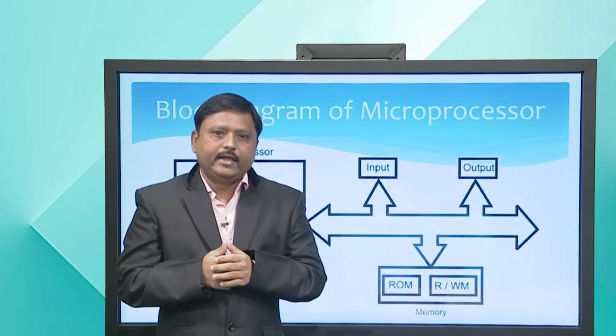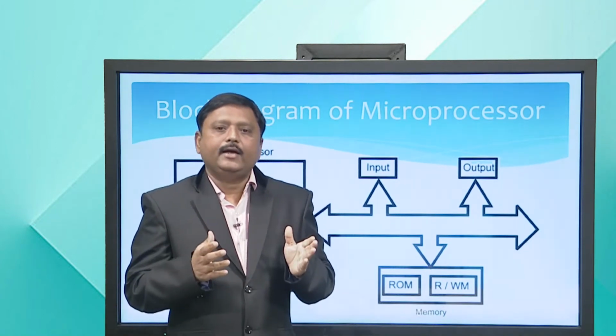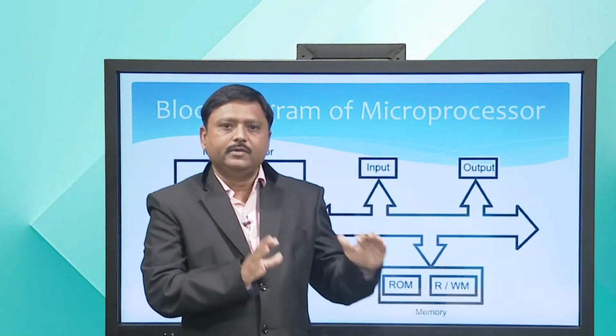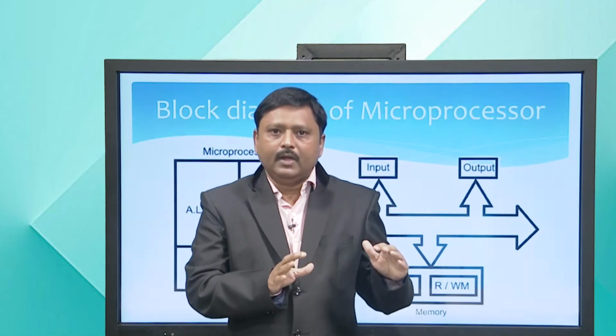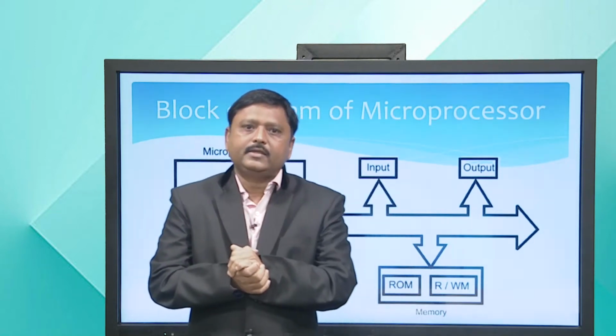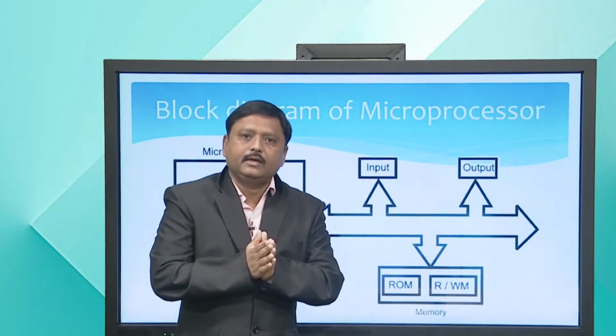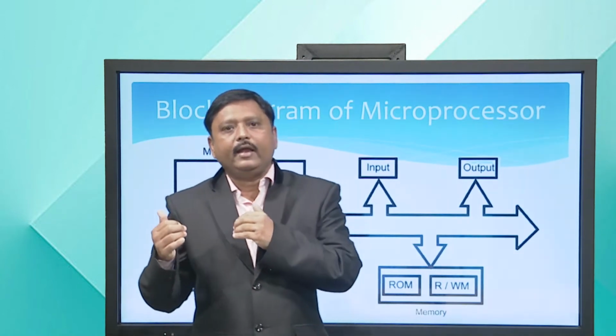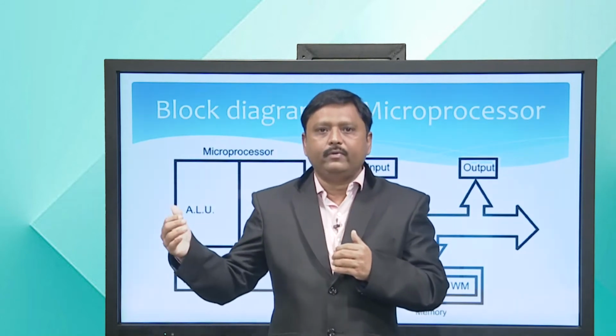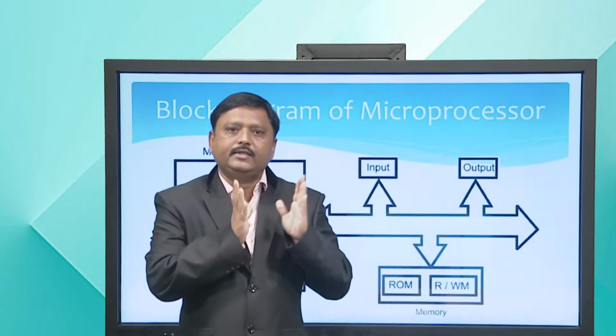One is called hex keyboard and the second is the keyboard that we are using, called ASCII keyboard. As the name indicates, hex keyboard comprises 16 numbers because hexadecimal consists of 0 to 9 and then A to F. So, hex keyboard has 16 keys.